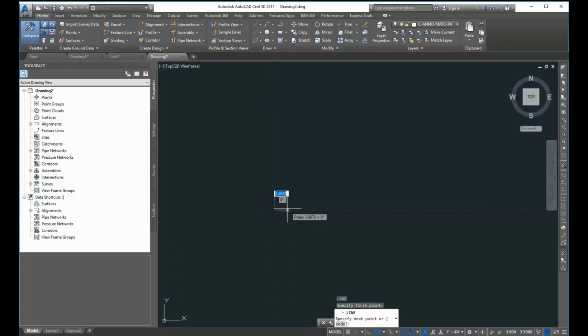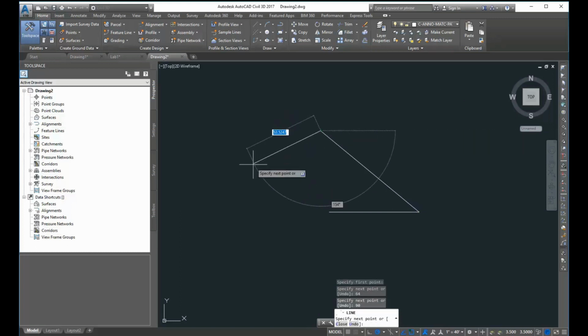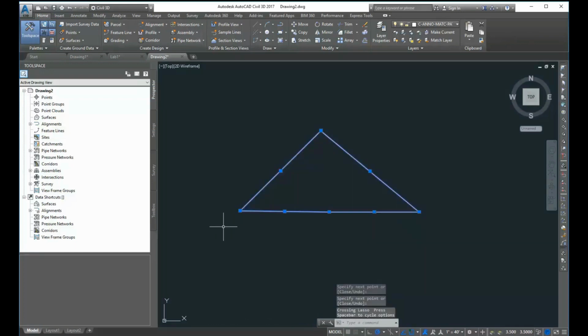And in the middle of the command, it's going to give me different distances, right? And I could force it to be 64 feet. So you can see it's going to tell me, if I were to left click at any point, how long it would be, but it's highlighted in blue, so it's telling me that I can actually override it. And I can finish up and delete.